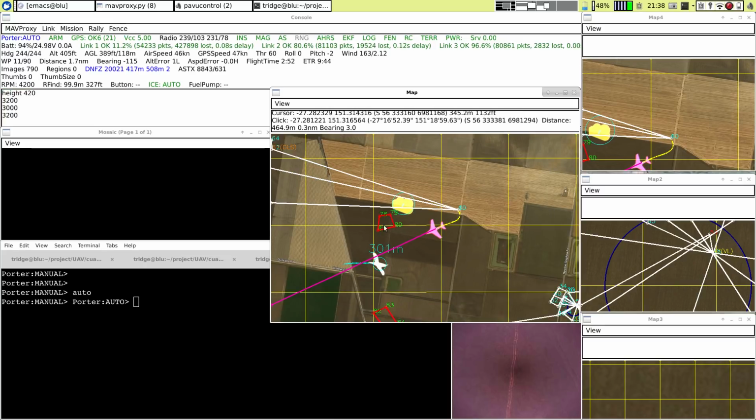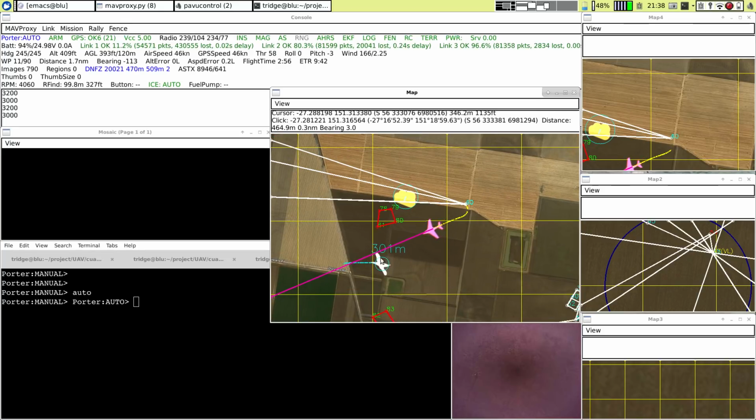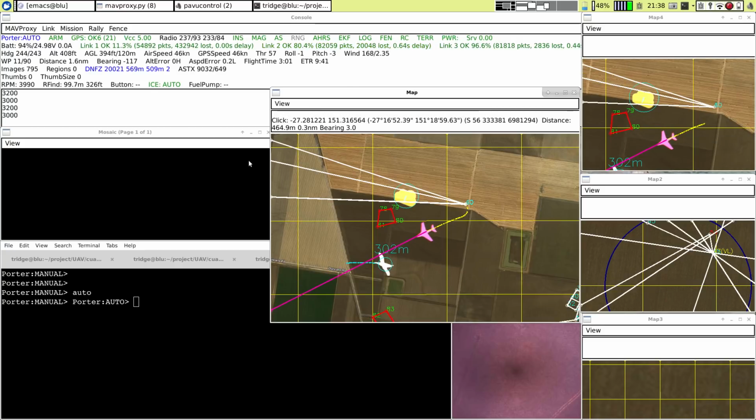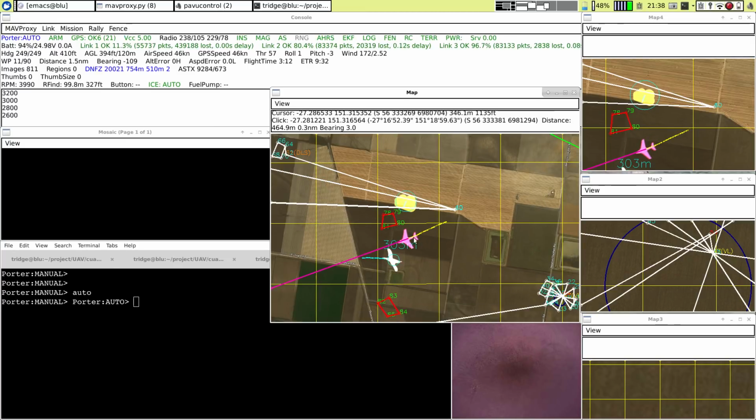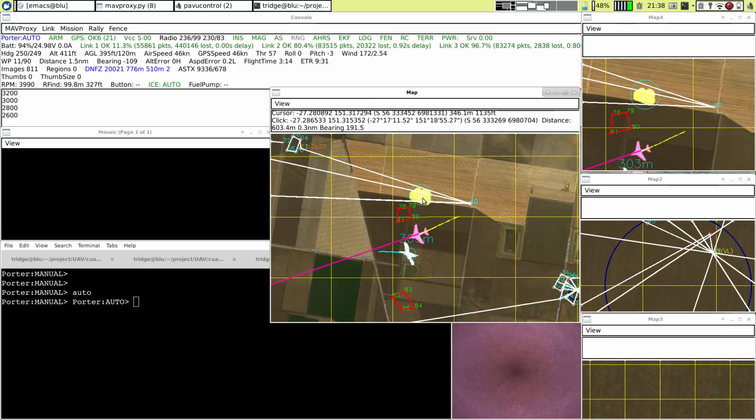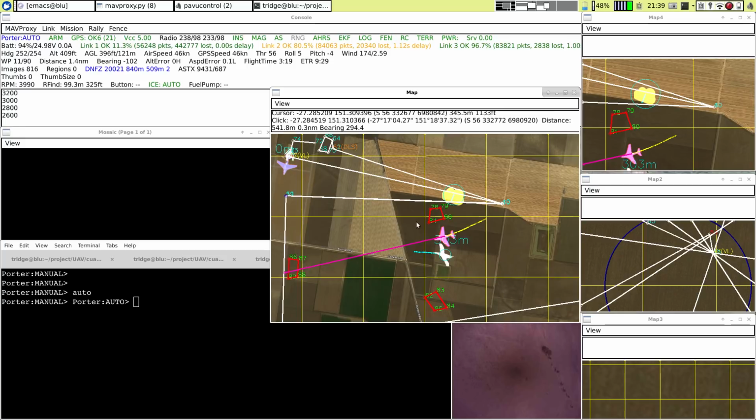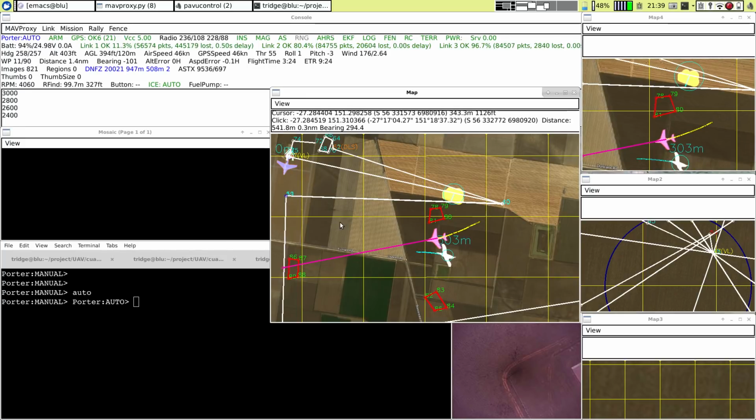It's also tracking around this exclusion zone here. You'll notice, however, it's quite happily going near this migrating bird, and that's because that migrating bird is at 301 meters above the ground, whereas our aircraft is 120 meters above the ground, which means we have enough vertical separation by the rules to not worry about that migrating bird. Now it's gone around this exclusion zone and avoided that cloud, and it'll go around there and track back to this waypoint to continue the mission.